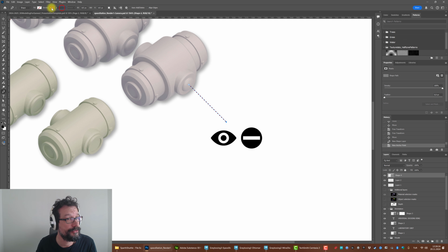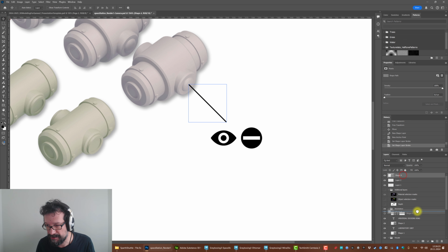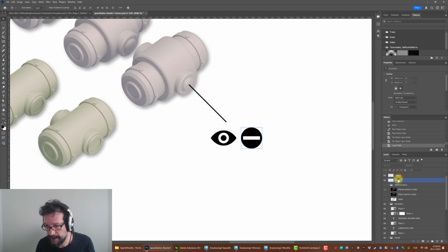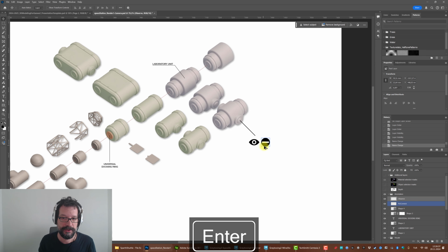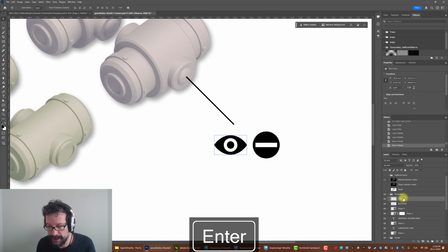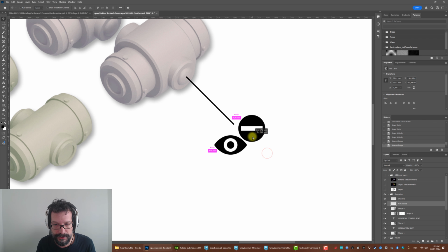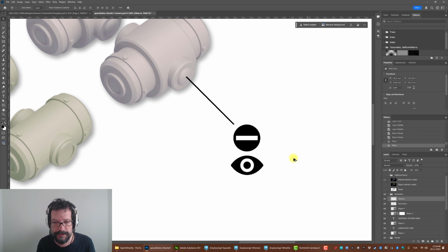And that's going to be 2 pixels and black and single line, if I remember correctly from our annotation standard that we have just set. Okay, and we can put these icons here, and this one is no connect, and this is observe. Okay, that's the purpose we are using these for, and we can choose a placement for them. Like this is no entry and also observe.